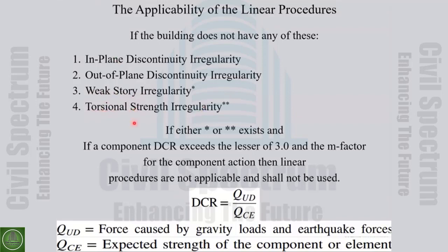Therefore, to have a general sense, the concepts are more important. We don't want to go into the details. These articles change from one version of the code to another, but in a general sense, the linear approach is okay when we don't have mainly strength irregularity. And if we have strength irregularity, we may still be able to use the linear analysis if the level of damage is not that much.